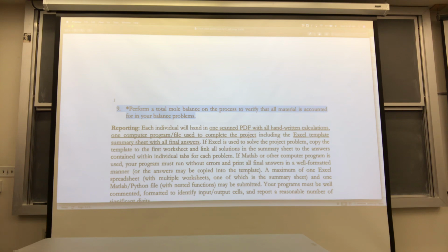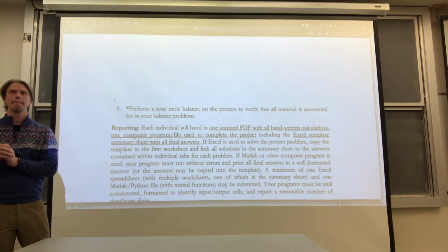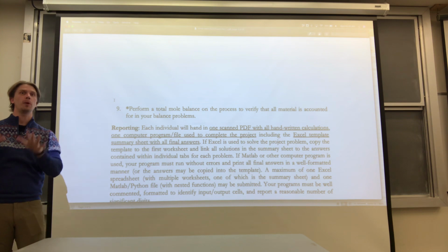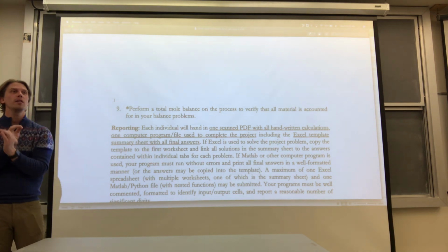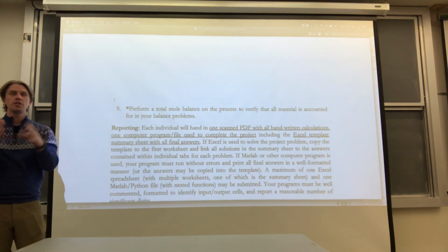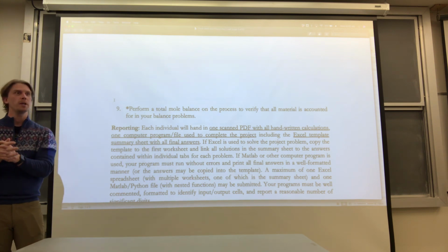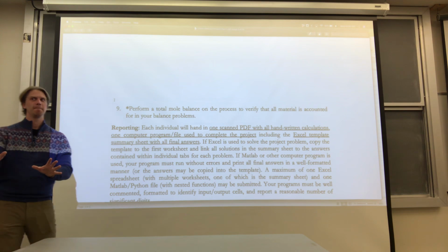Okay. Question. So what is part 2 going to be like? Just doing the energy balances in all the processes. But the thing is, right, the energy balances are super, super algorithmic. If you have all of the heats of formation and all of the heat capacities for all of the materials, it's just summation of molar flow rates and enthalpies. Add them all up, that's your Q, right?